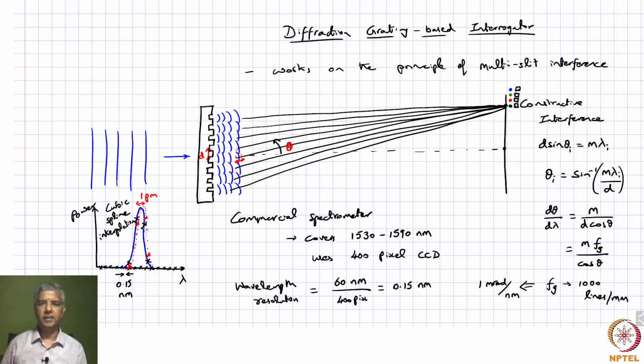But on the other hand, if you have a highly sensitive CCD array, especially let's say you are using a 14-bit CCD array, so you have 2 power 14 levels for each pixel, then you could keep at least the noise due to your ADC low, and if you have done other things right, you can maintain a relatively high signal to noise ratio.